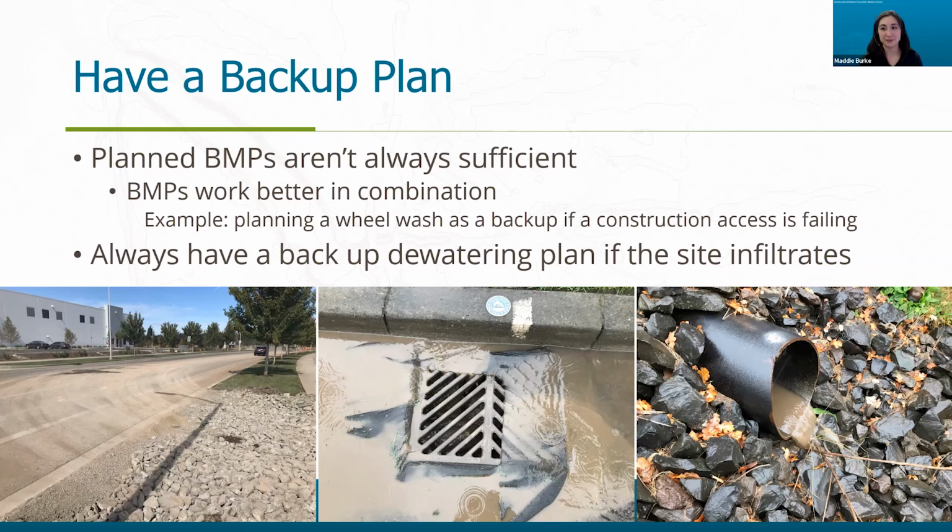And sediment tanks need to be sized and engineered. So this isn't just something that the contractor can on the fly dig a hole or choose a tank. This is something that you as the designer need to engineer for a backup plan.